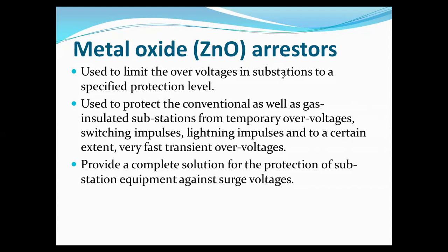It is not only extinguishing the arc, but also acting as an insulating material for that circuit breaker. So here also, in gas insulated substations, SF6 gas is used for the equipments as an insulator.